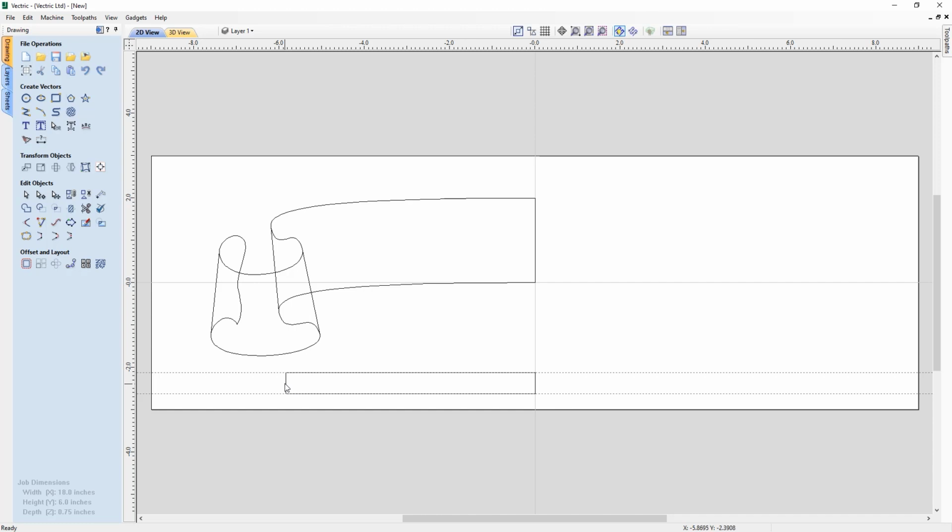So now we're going to use this rectangle to create the cross section that we're going to extrude to create this piece of our ribbon. Okay, and you'll see it right there. So let's select that and go into node mode by pressing N on the keyboard. Let's hover over this line, right click and say delete the span. Then we're going to right click on this line and convert that to a Bezier. And we can grab this node and use our cursor keys to slowly nudge that down. Now you'll see that we're getting the shape that we would need if we actually cut this across the middle and looked up from the edge. This is the kind of shape that we might want to see.